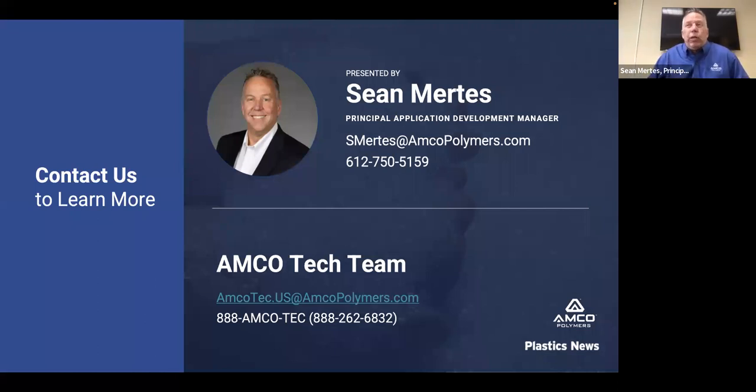I think there's really not much of a difference. The big difference between the cameras is the max temperature it goes up to, because you can get portable ones that go on your iPhone, but they only go up to say 250 degrees or 300 degrees. I think mine goes up to 700 degrees. So if you're running high heat polymers, you may need something higher. Then there's the number of pixels.